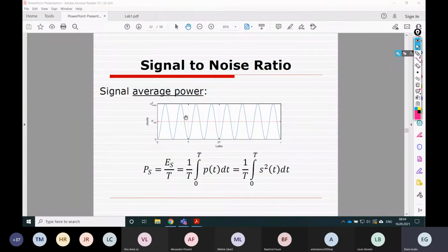For example, for a harmonic signal, the average power can be calculated by summing all the values of the squared voltage. So here is the square of the signal voltage. That's why here we have 0, and it never comes below 0 because a square cannot be negative. Basically, you just calculate the average value: add up all the points together and divide by the number of these points.